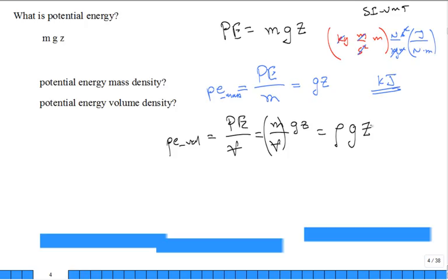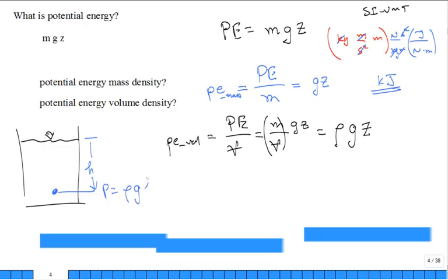That looks very familiar. We just came out of fluid statics, didn't we? Somebody says, here's a fluid tank, and I want you to get me the pressure at this distance. You say, okay, you're just going to have to tell me that depth at which it's beneath the free surface. And what will the pressure at that distance in that tank of static fluid be? Rho gh. Look at this. Rho gz. That is very familiar, isn't it? But we're talking about potential energy per unit volume.